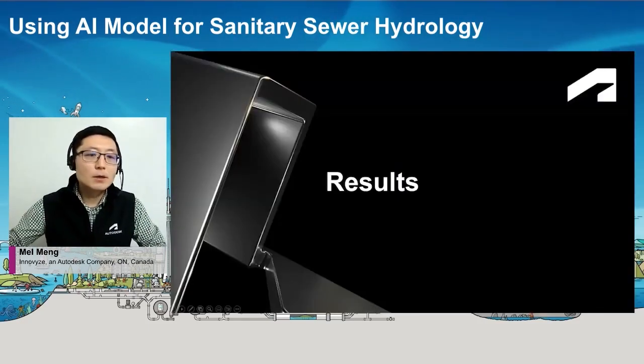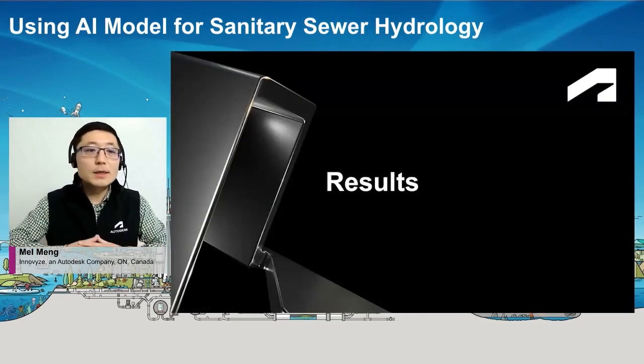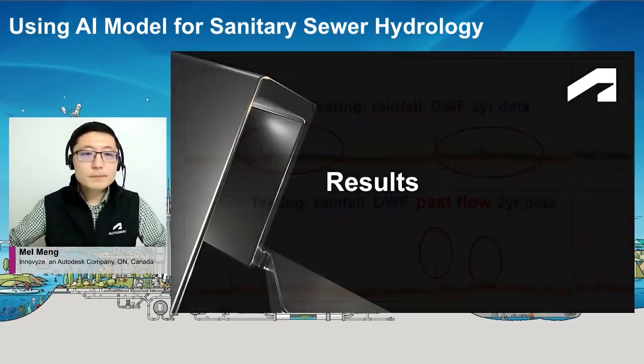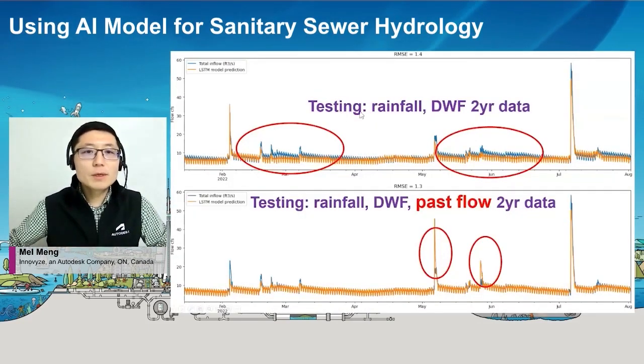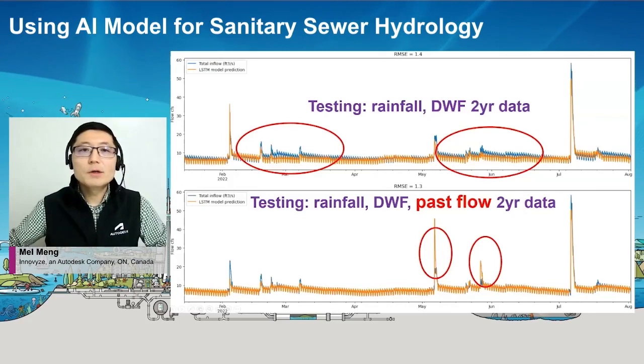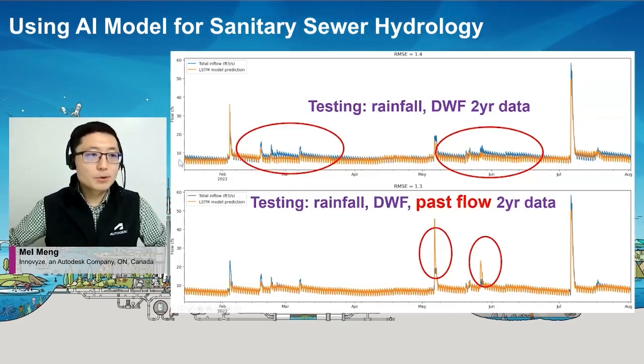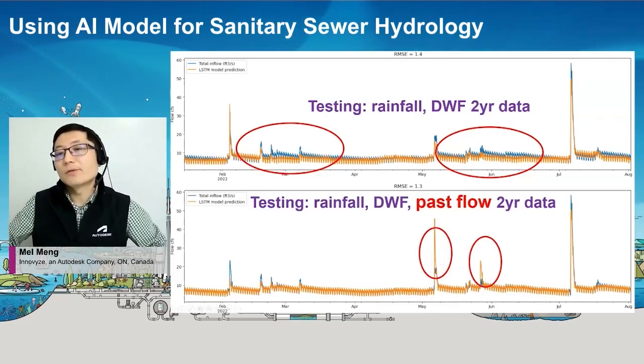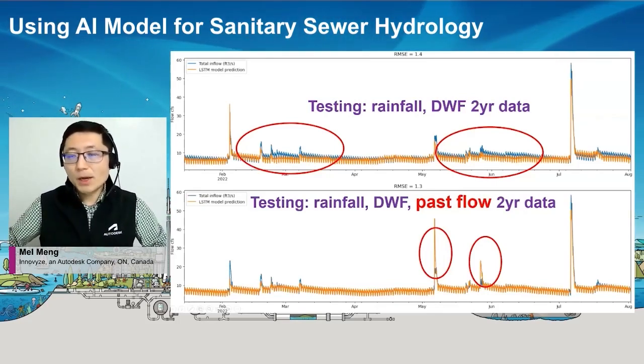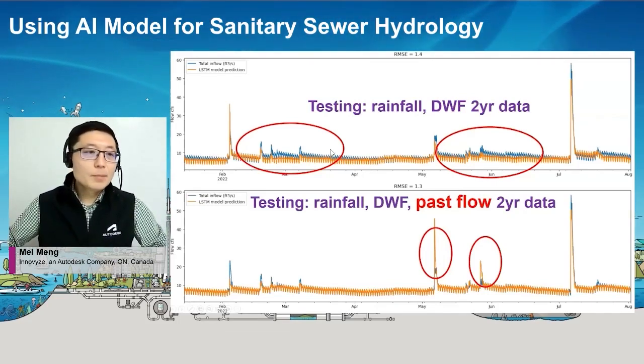Now let's see, after applying all these different techniques, how does it work? Let's look at the first one. For the first one, I just added the dry weather flow, calculated from Prophet. Remember, the first try I had was basically flat lines all the way through. So this is a huge improvement. You can start to see downward patterns here and there, but you will notice the groundwater is not well simulated. You don't see the ups and downs here.